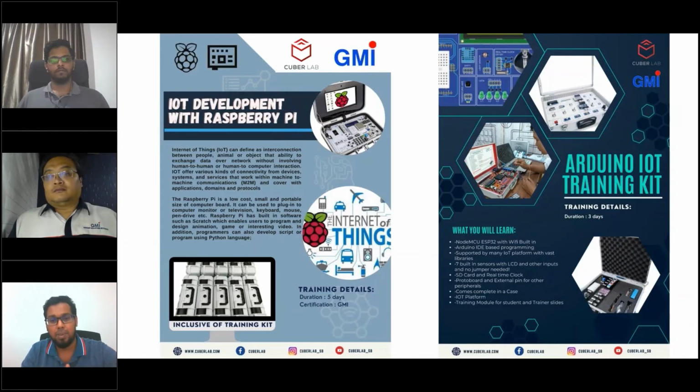If you need a high-speed application, then you have to go for the SCARA robot type, because it is really high speed and also high accuracy. So it mainly depends on the application. We have to study the whole application first before we can conclude which is the suitable robot. So there are a lot of criteria.